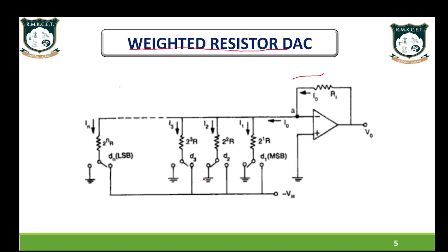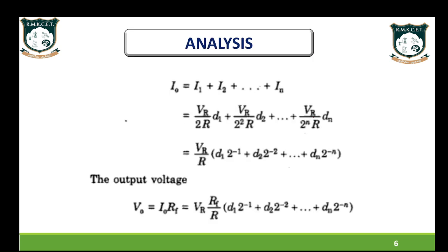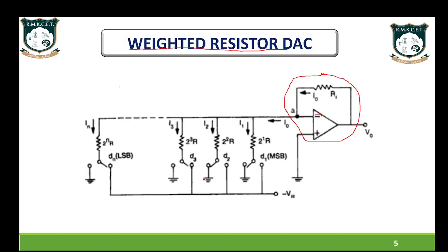In Unit 1, we constructed the inverting operational amplifier. So everyone draw the inverting op-amp, wherein at the negative terminal of the op-amp the input voltage is provided, and we have the negative feedback resistance connected from the output to the input. The positive terminal of an inverting amplifier is grounded.